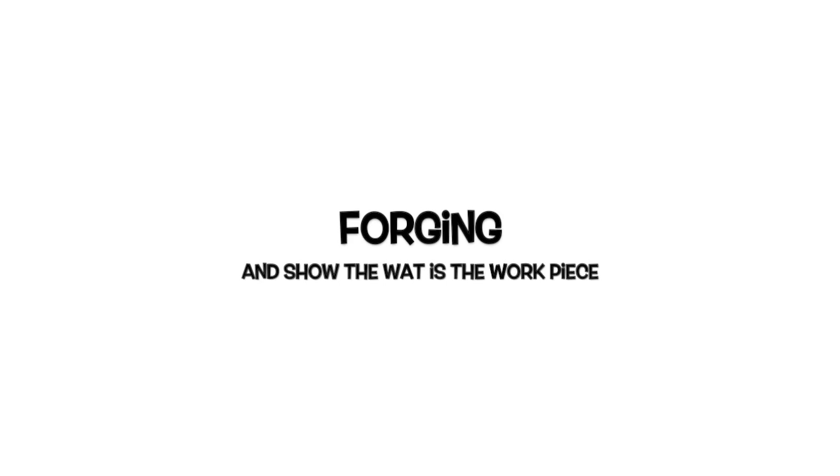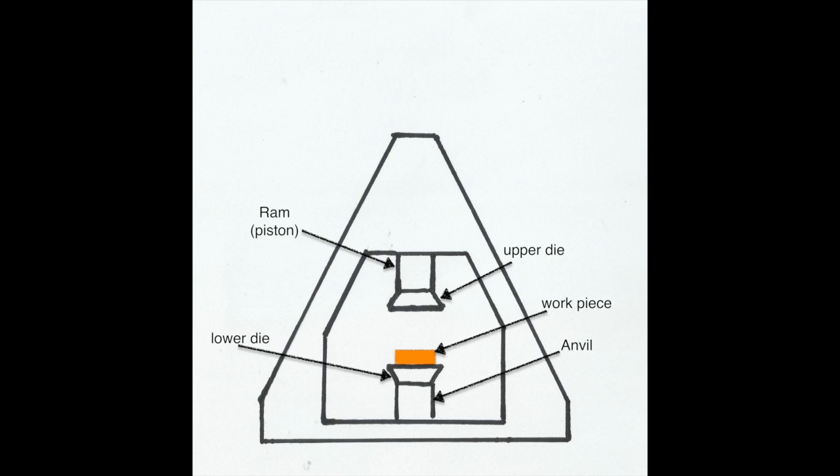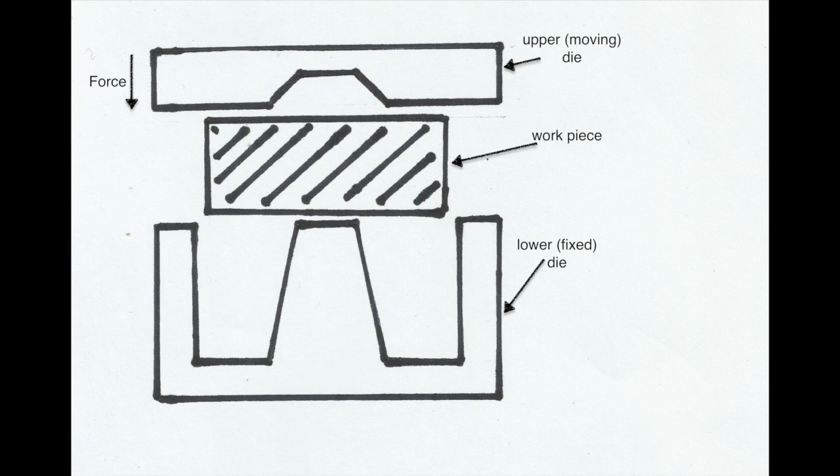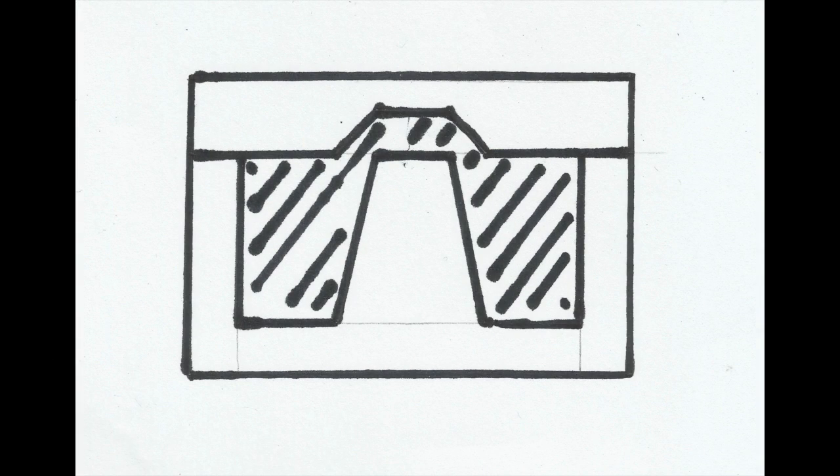On the other hand, we have forging, where we use massive compression forces generated by huge pistons to force the workpiece between two dies that squeeze it into its final shape. This high-stress process gives the final product a high mechanical strength and makes it wear resistant, thus increasing the product's reliability. Finally, we come to welding.